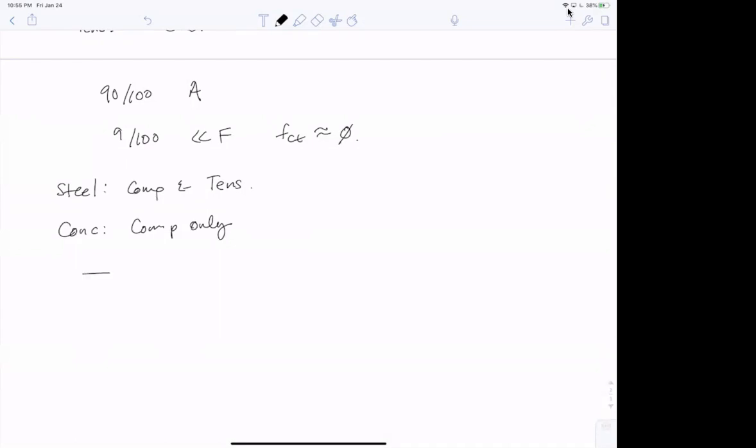So if you've got a beam like this, and you load it, and it bends, so it looks like this. You see the top is in compression, and the bottom is in tension. So when you make this beam, you would have to have steel in the bottom because that's where the tension is. That's reinforced concrete, and we'll talk more about this in a bit.